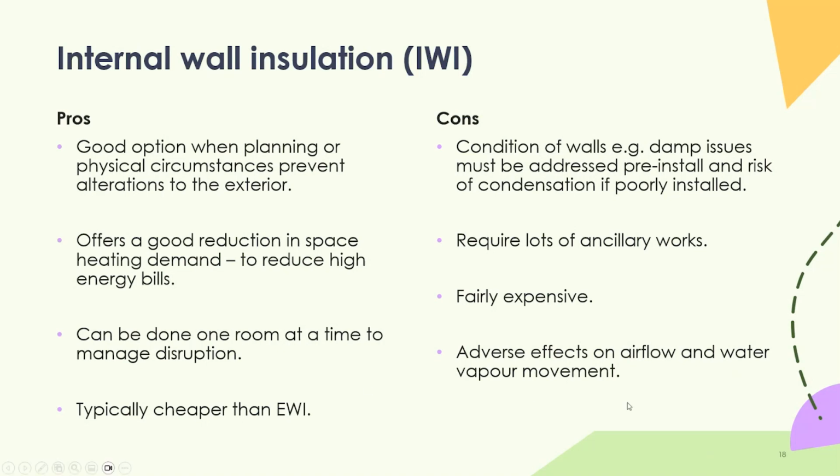So the last point, adverse effects on airflow and water vapor movement. So as I mentioned, when you're working on these solid wall homes, you really do need to be thinking about that kind of moisture open materials to allow for the migration of any moisture that's in the wall, maybe even trapped in the wall. It's difficult if you're retrofitting properties in the colder winter months to be able to say, well, the wall's dried out. 99% of the time probably not dried out. So you do need to have the materials you're using allow a wall to dry out.